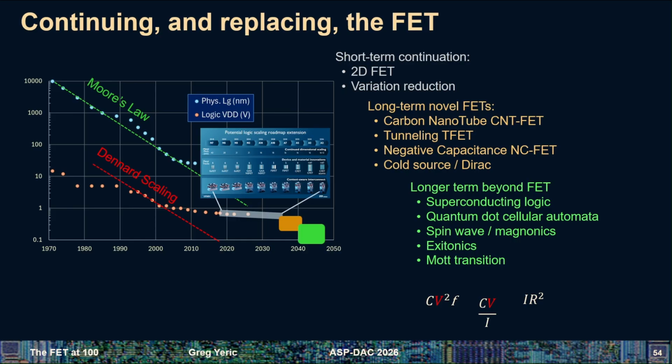So we're all the way back to the beginning of the talk where Lilienfeld knew that you need gain, meaning that the amplitude of the signal coming into a transistor, the transistor should be able to make a higher amplitude output. And when you look at circuits, say you have a path of transistors that you have in a CPU, a logic path, you're going between an AND gate and an OR gate and flip-flop and these different parts of logic. Well, you string everything from the input to the output, and you got like 20 transistors you have to go through from input to output.